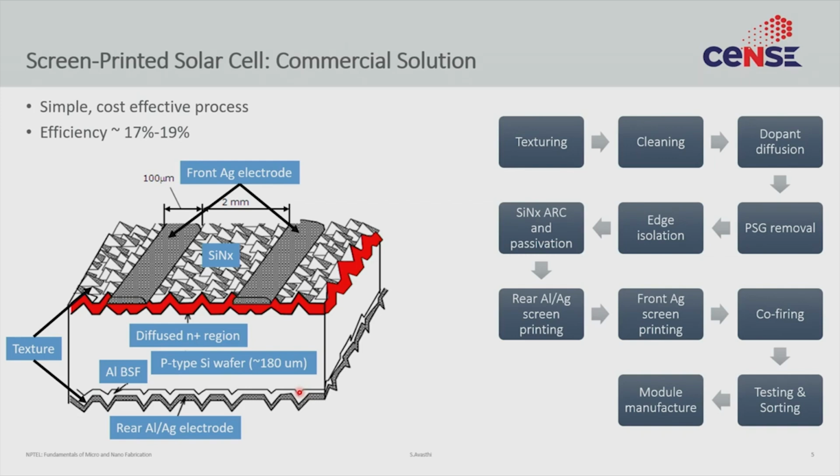Okay. The other thing we notice is the front electrode. So once again, we have a front electrode where some part of the device is covered with metal. And the thickness of the metal top electrode in this case is around 100 micron, which, if you think of microfabrication, is huge. I mean, we are talking about nanofabrication at Intel. We have critical dimensions of 10 nanometers, but that is not the goal here. The goal here is to do what is barely enough, and 100 microns for silicon solar cells is plenty.